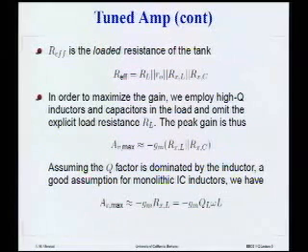Let's just say we want to maximize the resistance of the load. If you look at this expression for R effective, in order to maximize it, we should make the individual terms as large as possible. Now, R out is the R out of our transistor. We can probably play with the L of the transistor. We can play a few tricks to make R out as large as possible. But it turns out that for a lot of circuits, the R out of the transistor is actually quite large. Let's say it's kiloohms range. On the other hand, the R's of the inductor and the capacitor are something we have to live with. It's the manufacturer that gives us these parameters effectively. So the only way to maximize the R effective is to basically maximize RL.